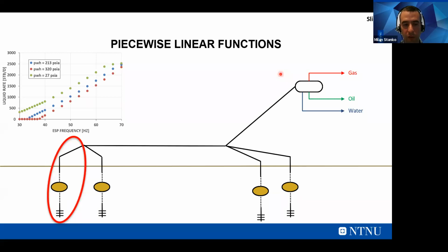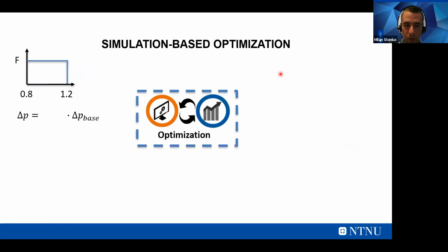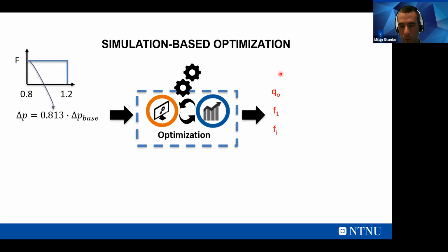Yeah, stochastic you typically use when you have some uncertain parameters and you want to find the optimal considering those uncertain parameters. We didn't use that approach here, but we simply used sampling. We assumed that the input, or the model, is uncertain, and then we used sampling. Because this runs in 7 seconds, you can do 10,000 iterations very quickly, in less than 2 hours.